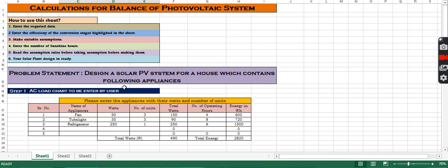However, you can assume any percentage efficiency, but as those elements are static in nature, the efficiency is handsomely good. Then you have to enter the sunshine hours. Usually it is 4 to 5, maximum 6 hours, where we can have enough penetration of power from the PV.